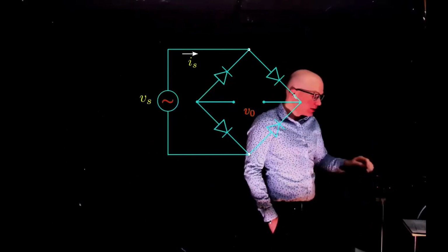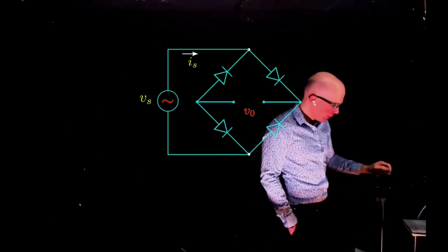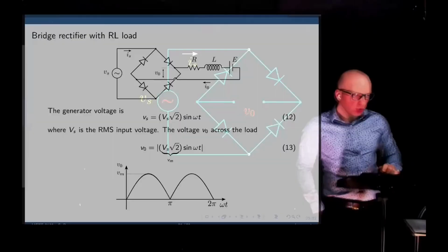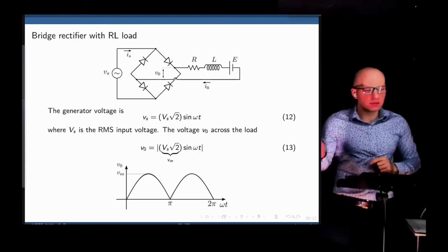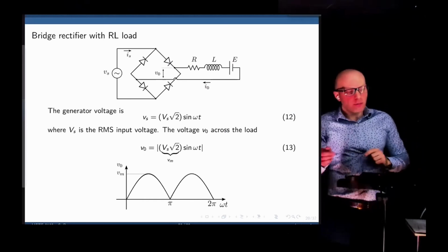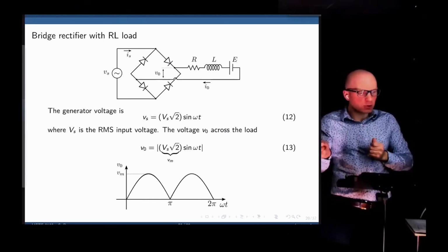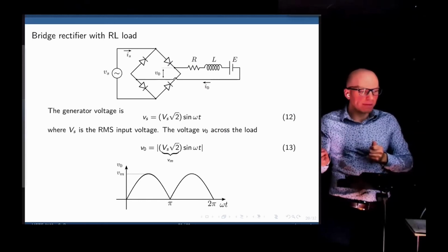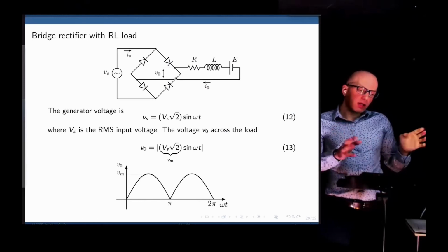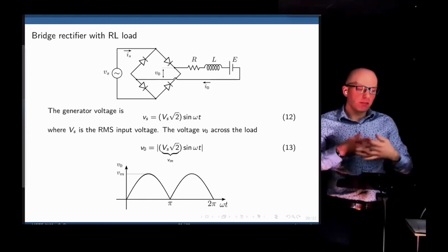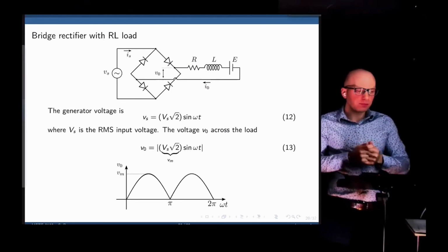But the instantaneous voltage would look like that, the bottom one. If you put an oscilloscope, that's what you read, the bottom voltage. A multimeter is likely to give you an indication of the RMS, depending on how it is set up. Okay, got it. Thank you.